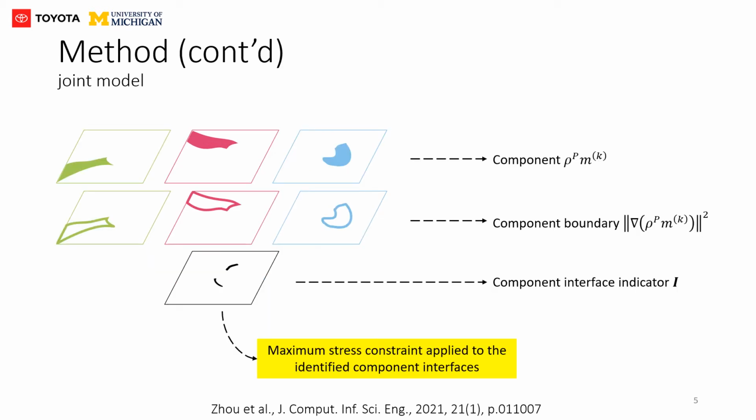In multi-component topology optimization, both the overall base topology and component partitioning evolve during optimization. The identification of component interfaces is especially challenging when the density and component membership design variables are still blurry, which is typically the case until very close to the end of optimization.